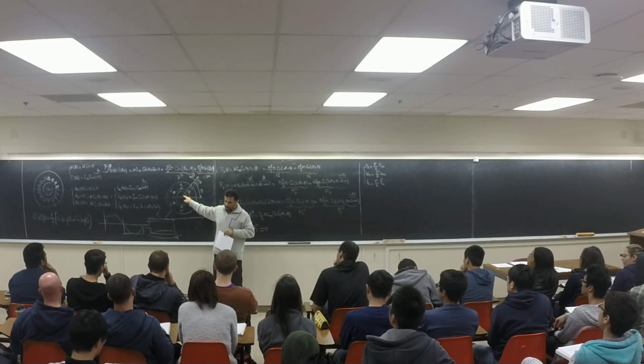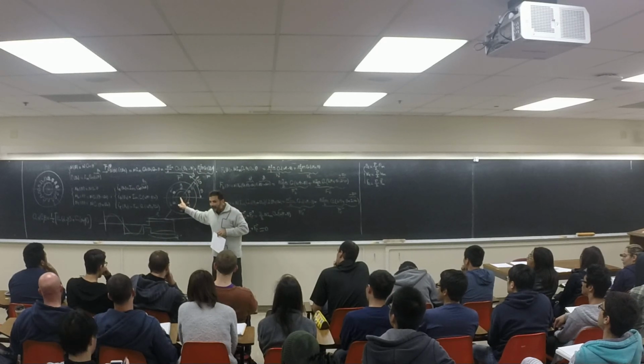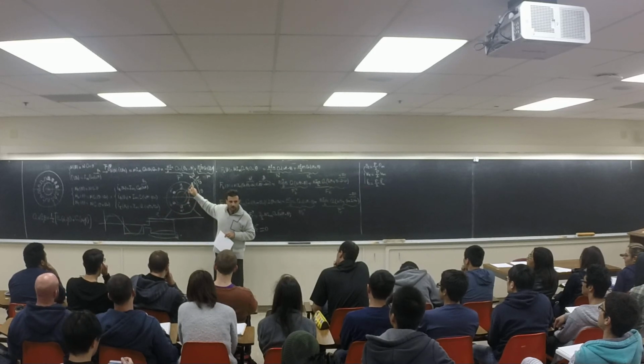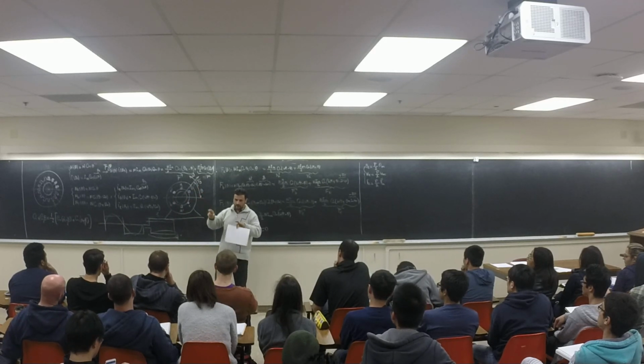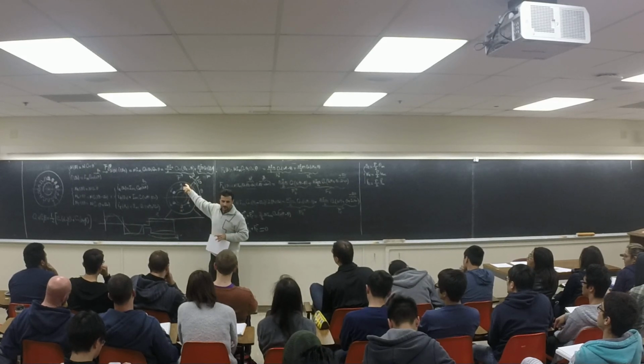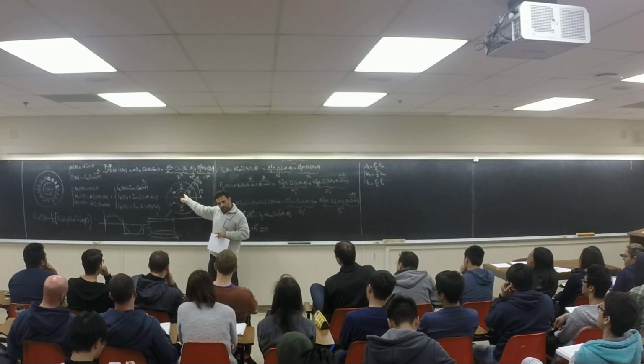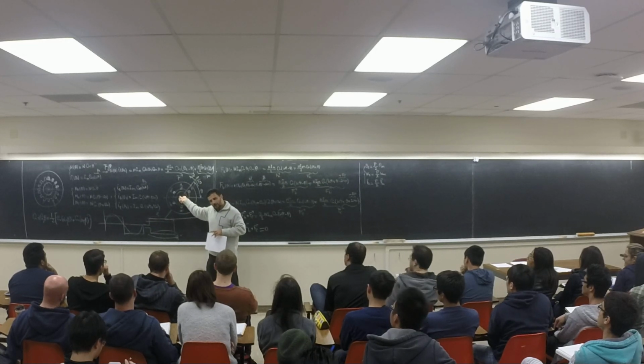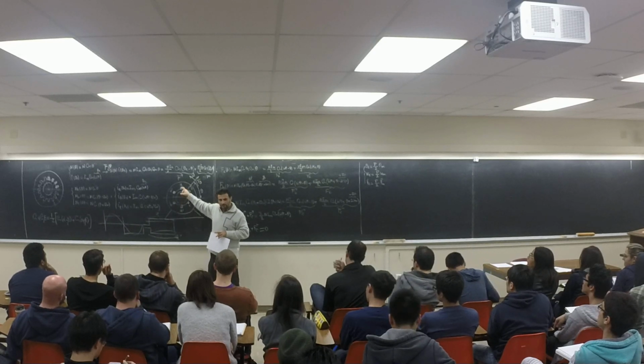How much? 50 hertz. So the magnet created by this rotor also has to rotate with 60 hertz, if it's going to be a steady state rotation, right? This magnet and this magnet should rotate at the same speed, right? So I'm rotating this one with 50 hertz, right? So the current in the winding should have another 10 hertz, right? 10 hertz plus the 50 hertz I'm rotating.